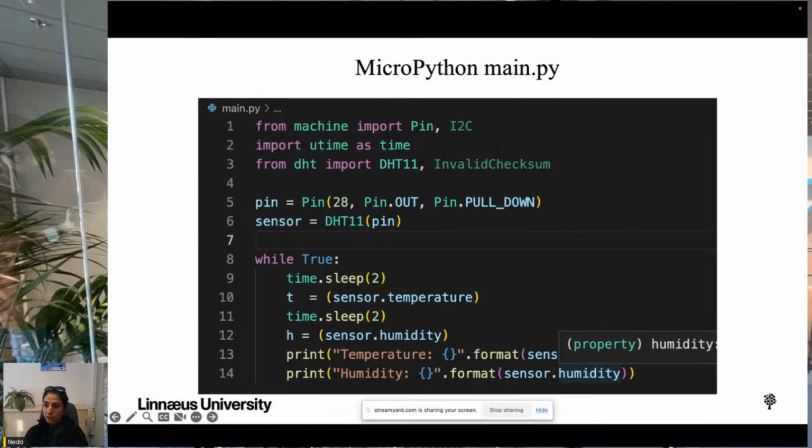When a pin is not being actively driven, it can be susceptible to noise or interference that can cause its voltage level to fluctuate, which can cause unpredictable behavior in a circuit. By enabling a pull-down resistor on a pin, we can ensure that the pin is pulled to a known low voltage level when it is not being actively driven.